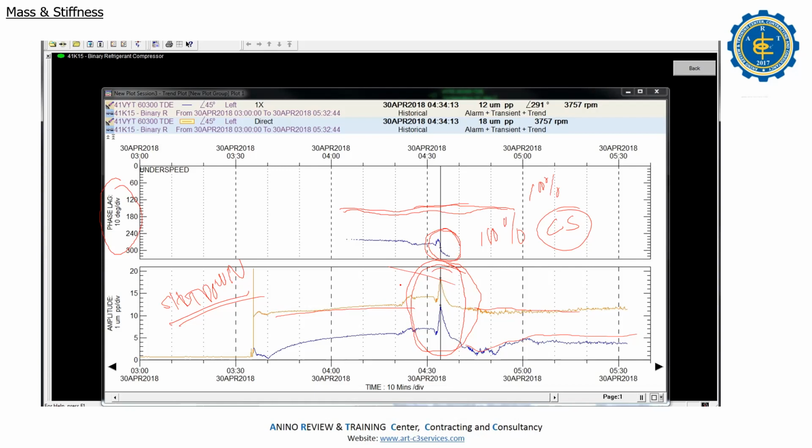If it is critical speed, you will have a phase change. But if there is high vibration and no change in the phase angle during the high vibration, then it is not the critical speed, meaning there is a problem with the equipment. That's why, with my superintendent, sir, there is a problem.